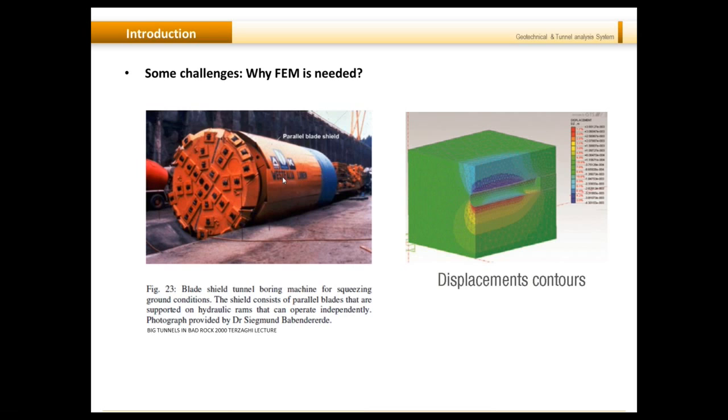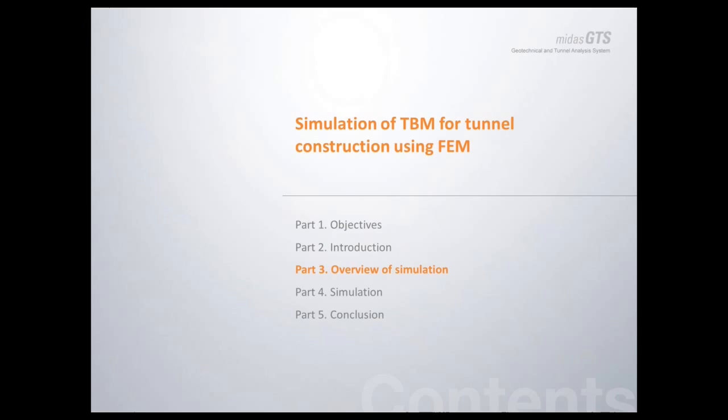If your excavation is halted in between and you are applying some special types of hydraulic jacks to stabilize the excavation, then you can apply those kinds of temporary supports also if needed. So very important for numerical modelers is that in order to simulate these new developments, you definitely need a good 3D modeling tool to replicate the effects of the new developments in tunnel boring machines.